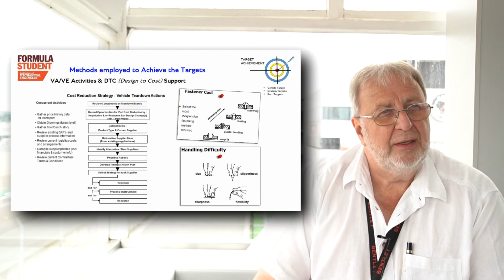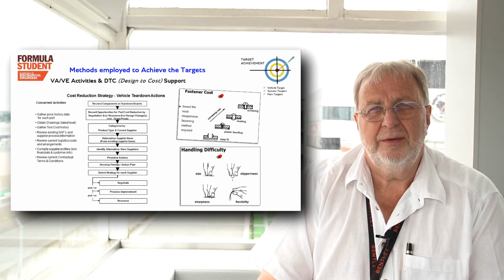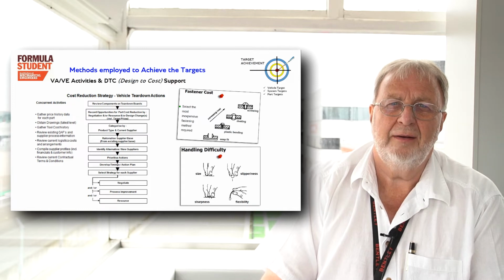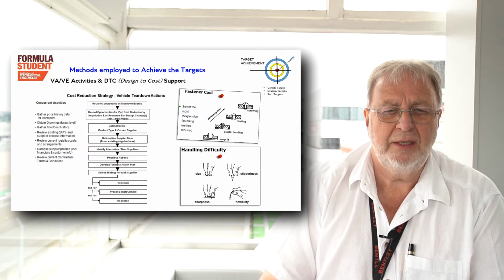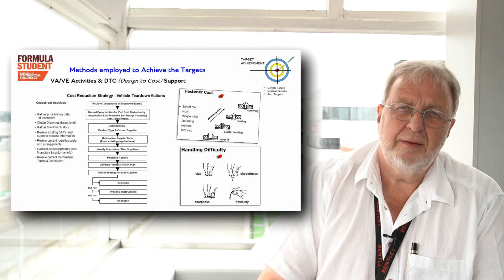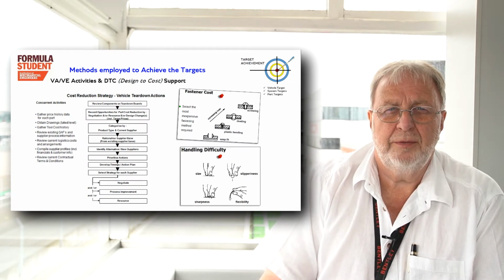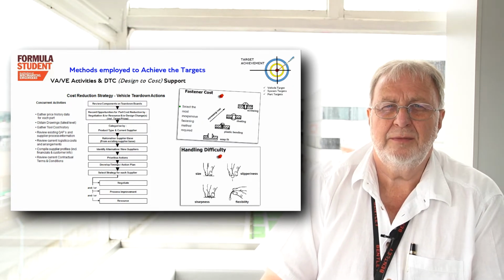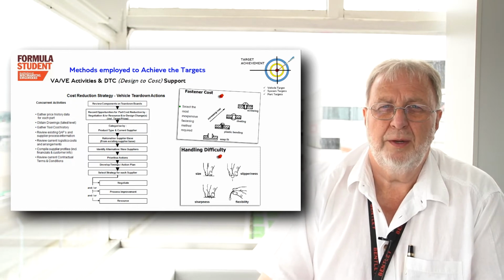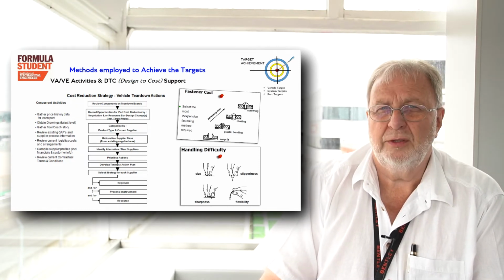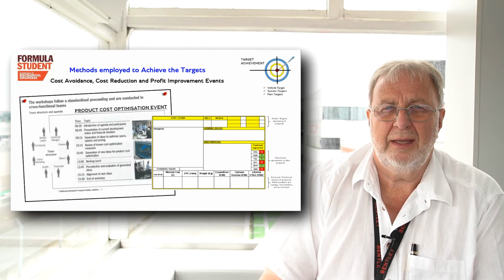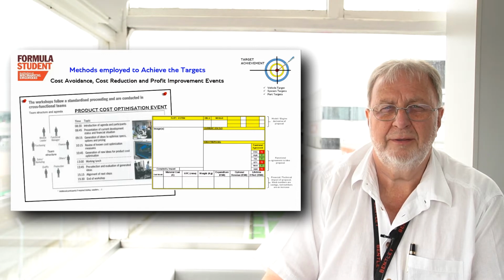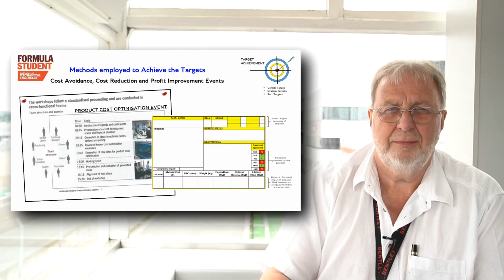because we will be looking for them. In our industry, we're not just looking at improving the base cost of the product, we're also looking to improve the profitability of our end product. And that can be achieved in many ways. By looking at the volumes you're asking your suppliers to produce, instead of amortizing the setup times to produce maybe one part at a time, maybe order 2, 3, 4 parts. Let them set up once and amortize the cost of that time over the 4 parts rather than doing it for every part. Again, it's lots of simple ideas.